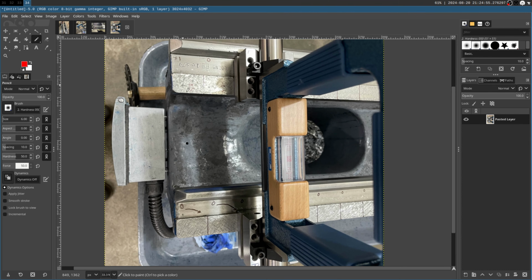And it's this measurement. Same sort of thing. This I'm using, I think, the back or the front. I can't remember. I'm probably using the front because I start off here. And I basically move the level down and I do the same thing. And now I'm getting readings across these 2 points, across the planes. So now, if these were both perfectly flat, but they're not in the same plane, they would eventually start to deviate here. Because one would be going up and the other would be going down with respect to each other, right? If that makes sense. Okay. So what I do is I go and I take all of those measurements.